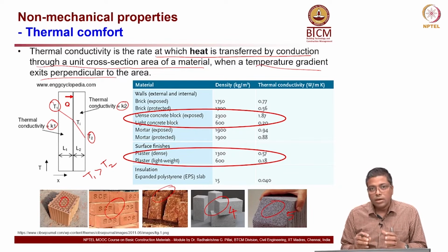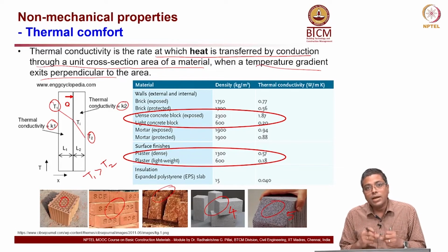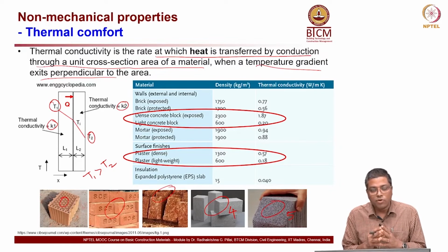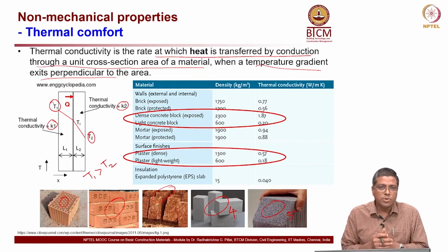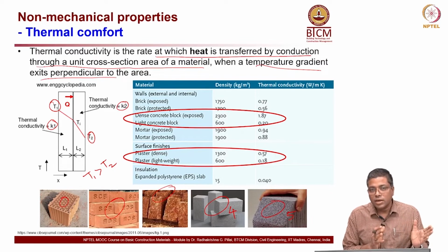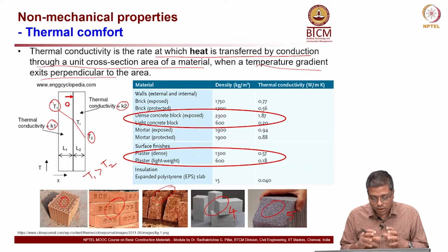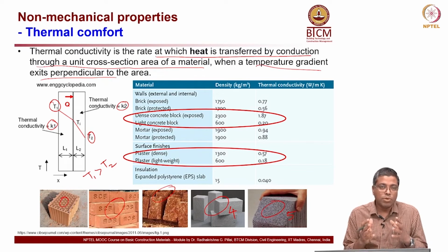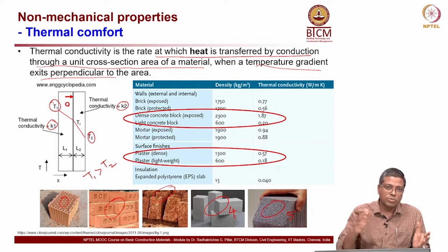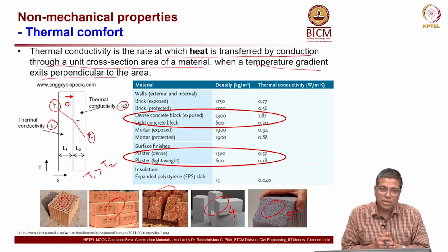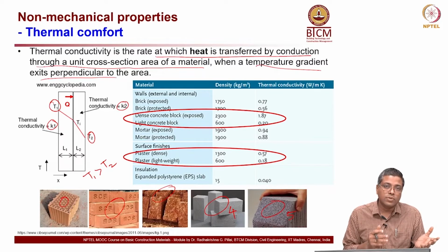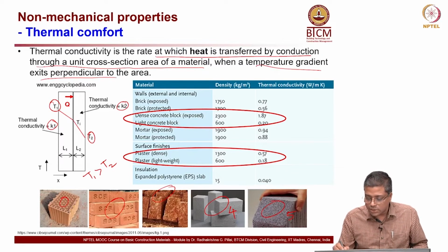It is made by mixing the concrete with alumina powder, and during the reaction hydrogen bubbles are formed, and then you have a lot of these well distributed air bubbles inside the brick, and that is a very lightweight brick also. That also helps in preventing the exchange of heat from one side to the other, both heat and noise. So, if you have air voids inside your brick, it is good for noise control from one room to the other, and also for thermal exchange from one side of the wall to the other side. You can look at this example here.